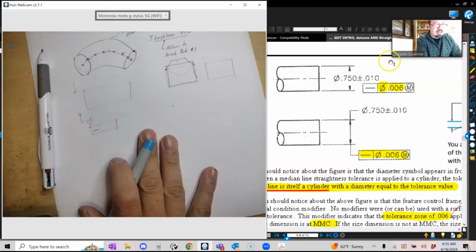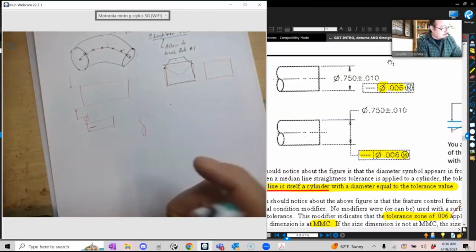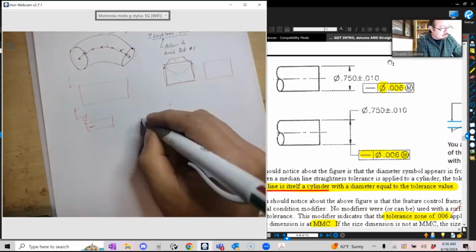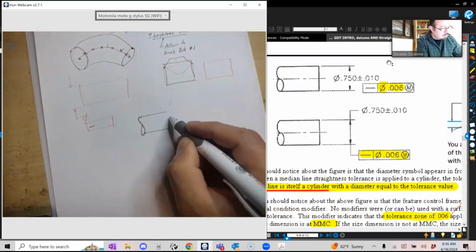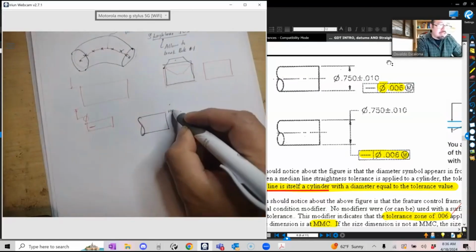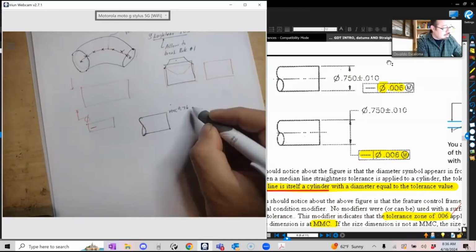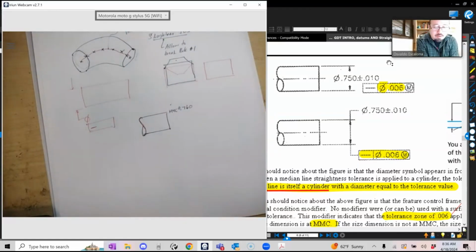So let's rewind, and we're gonna put my pin. Put it there. And it has a maximum material condition here. Seems to me 0.76, right? 0.7 diameter, 0.76 here. Okay. 0.75 plus 0.01, 0.76. It's telling you, you know what?